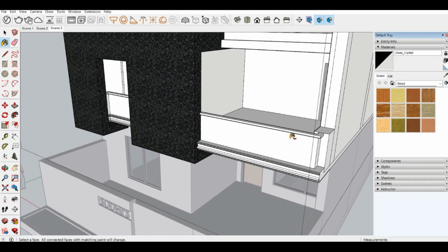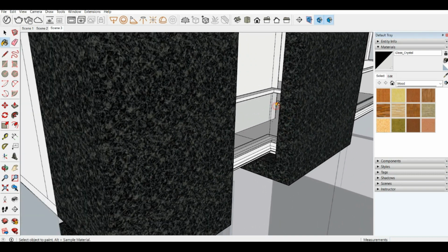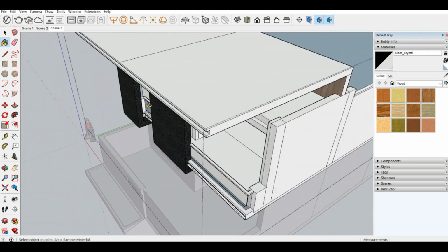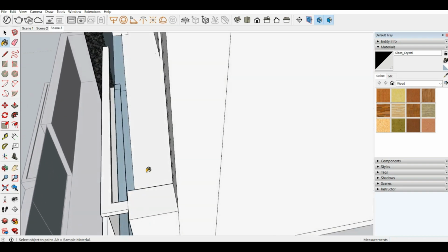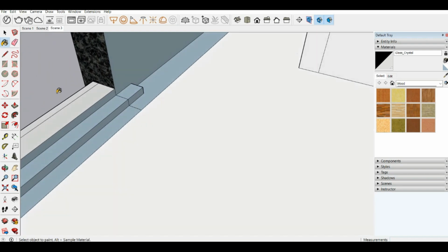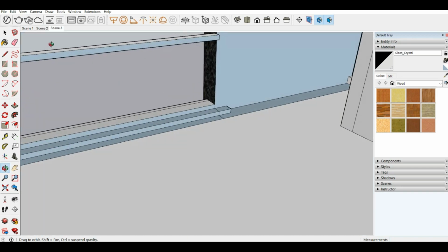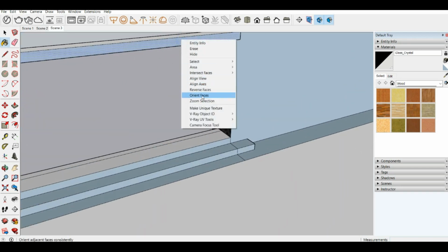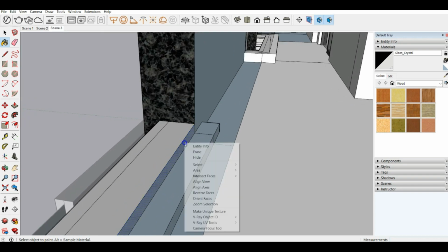Now I will apply it here at these railings. Oops. Just be sure that you apply it just right, like check if some geometry is left or if some extra geometry is painted. I'm also gonna check for any surfaces that are left. Okay, here there are some surfaces of the box of the dropper that were left earlier. Let me do this first, then we will go for the dropper again.